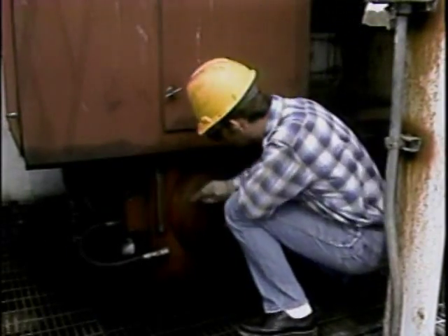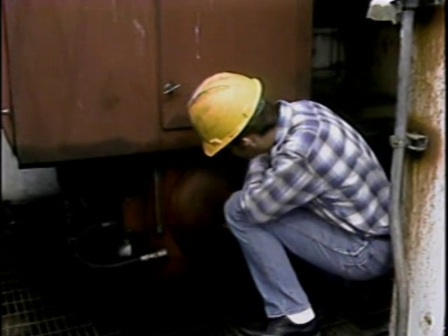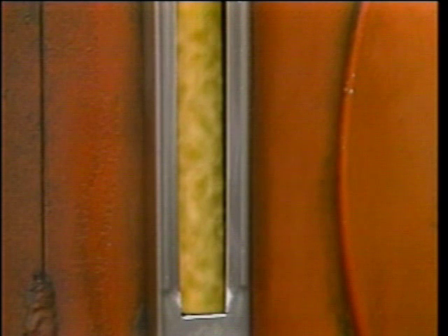When water is mixed with hydraulic fluid, the mixture can turn into foam. This foam causes the actuator's piston to have a spongy movement, which can cause problems with valve positioning. Operators may be able to detect water contamination by looking at the hydraulic fluid. This can usually be done at a sight glass on a hydraulic supply reservoir. Hydraulic fluid is normally clear. However, when it's mixed with water, the fluid becomes milky.